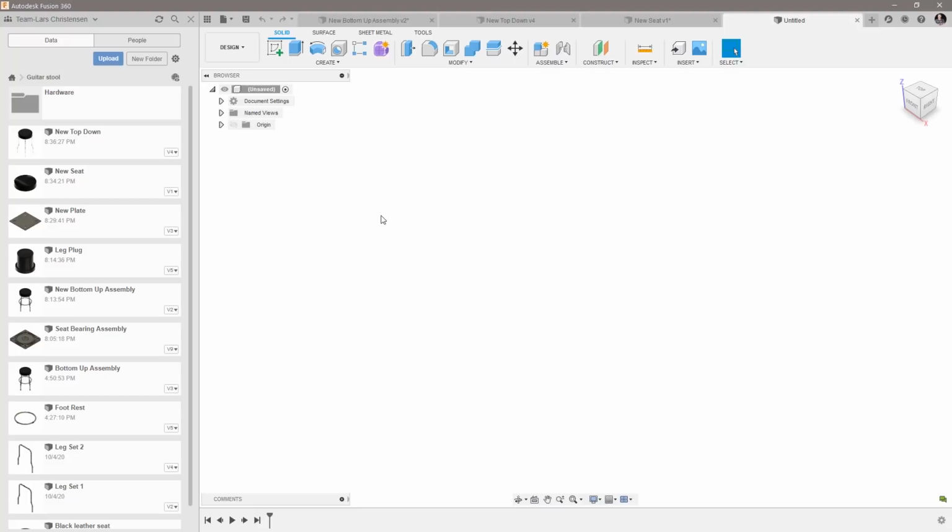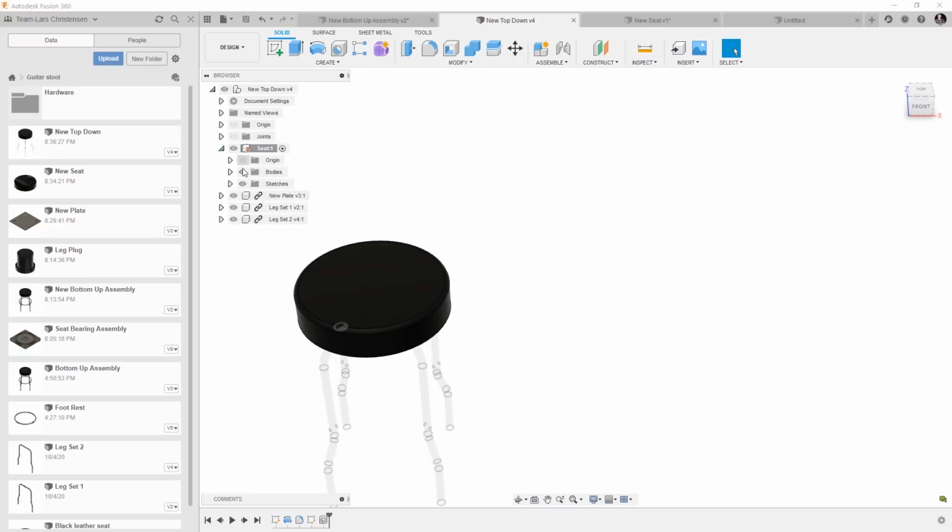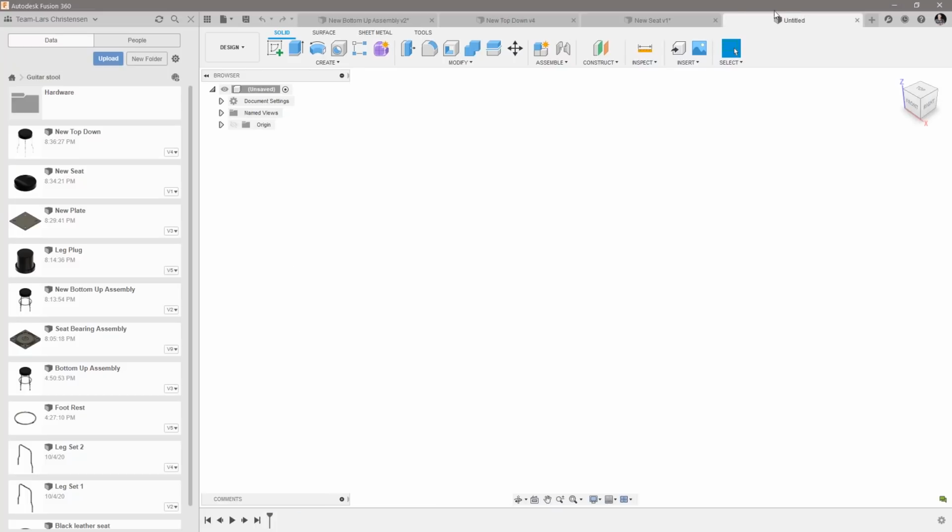Skeleton modeling actually is kind of the same as top down, but we're starting out by using a sketch to drive everything from. When I did this top down originally, you saw when I did the seat, I placed my sketch in here for that seat like we're normally modeling.